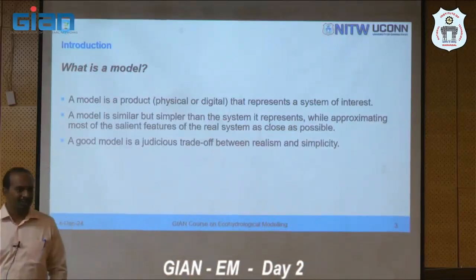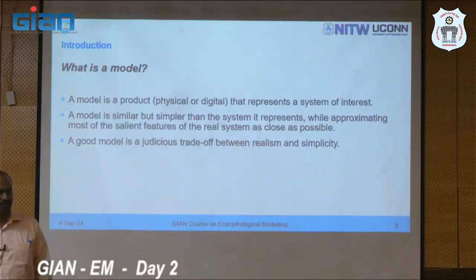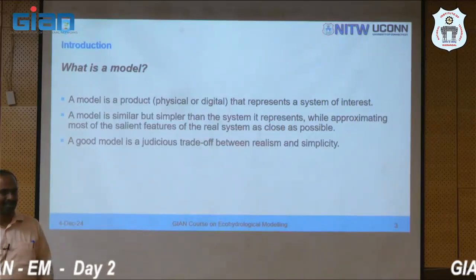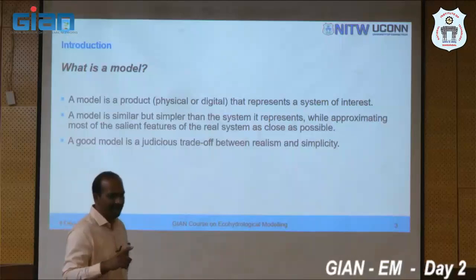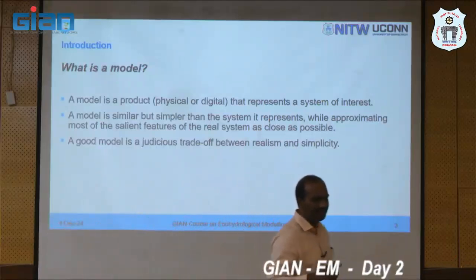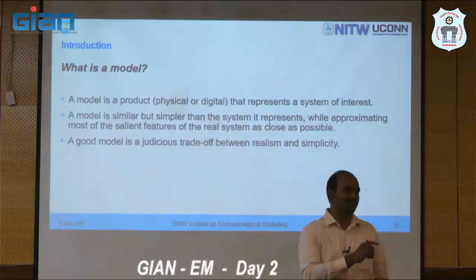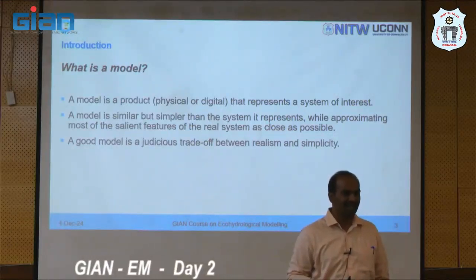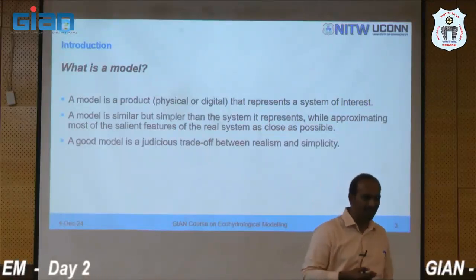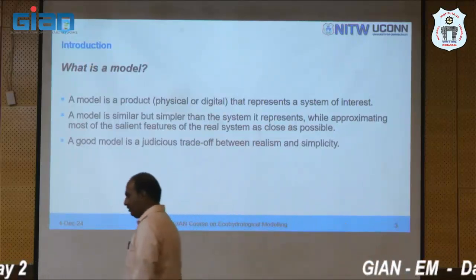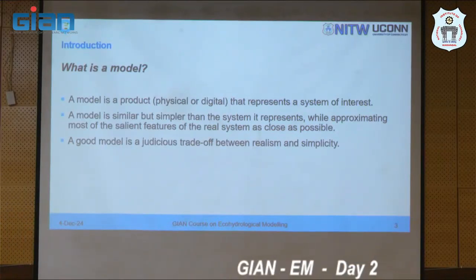So that is where I come back to this part, whether the result is good or bad. If you are interested in accurate prediction of stream flow, 95% accuracy is good. I am not worried about whether my evapotranspiration is getting simulated properly, whether my groundwater recharge is getting simulated properly, or soil moisture gets simulated properly, right? And that is where I say you don't need SWAT for that, right? You don't need a model that comprehensive. But 95% accuracy in stream flow prediction is not good if you are interested in the intermediate part.